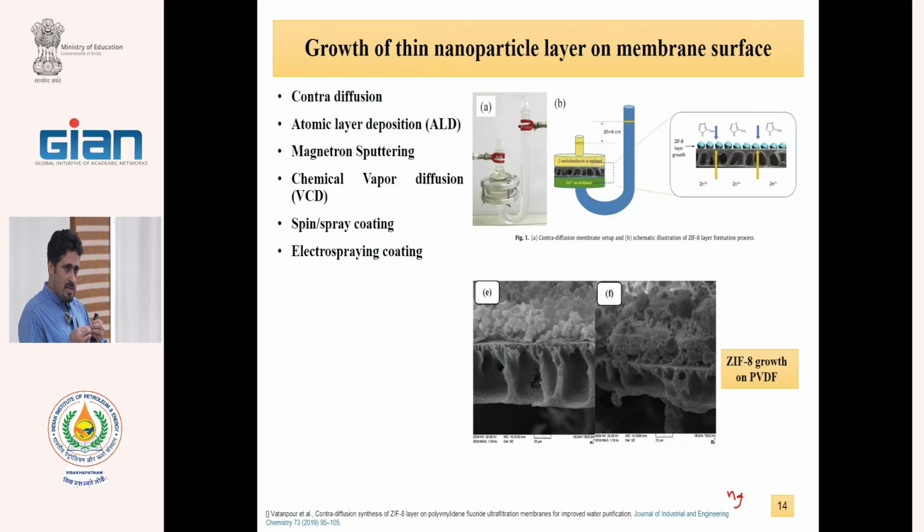In CVD, because both gases come together, in some cases we have a non-uniform coating, because in the first space we have a high reaction rate due to high concentration, and as it goes along the surface, because of the reaction, the concentration is reduced.